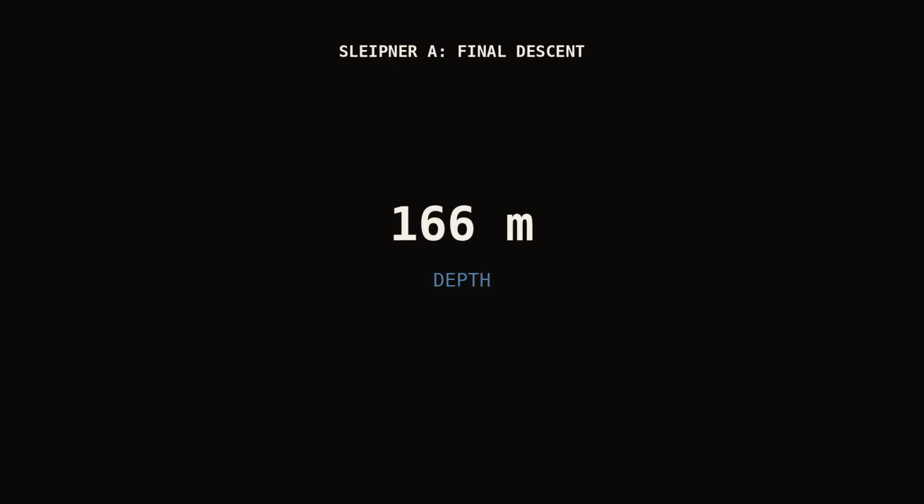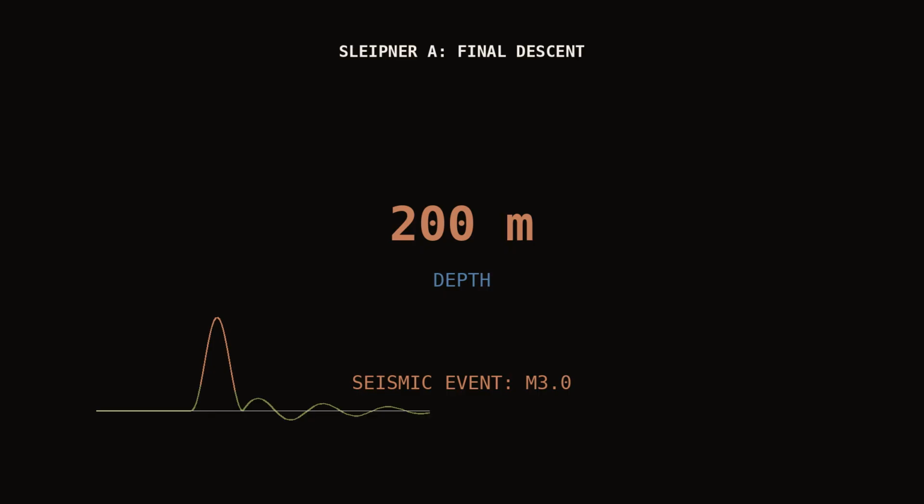The accident triggered an industry-wide overhaul. Mandatory mesh convergence checks and independent peer review of finite element analyses became standard practice in offshore construction. The case entered engineering curricula worldwide, a canonical example of what happens when you trust the output of a model without questioning the model itself.